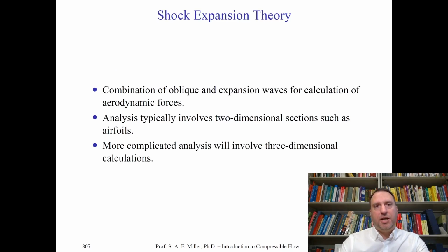Let's now look at shock expansion theory. Indeed, it's the combination of shocks and expansions for the calculation of particular aerodynamic forces. So now in this class, we're going to take our oblique shockwave theories, which we previously developed, and our newly developed tool of expansion waves of Prandtl-Meyer and apply them to particular problems to find the variation of static pressure acting on a vehicle as it moves through the air to estimate lift and drag.